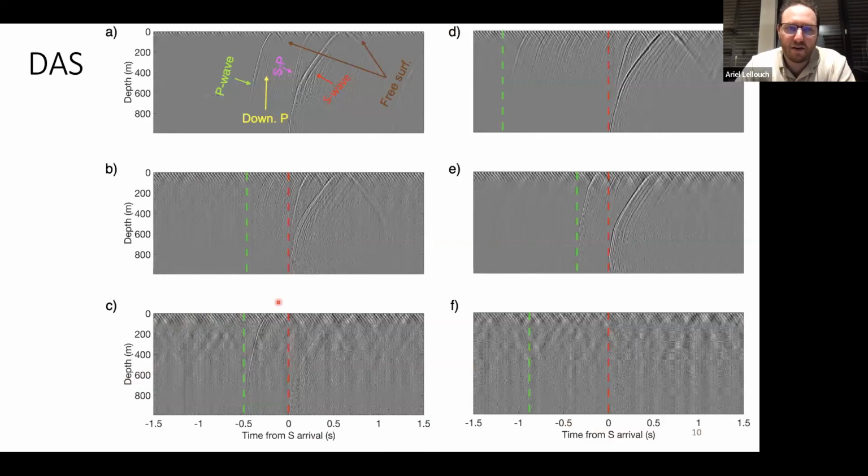If we look at DAS, I think things are easier to understand. So just so we get used to these plots, this is the depth, so it goes from 0 to about 1 kilometer down. This is time. The strong events that were visible on the surface, we can see a wavefield that we recorded over the DAS. So we can see this phase here.